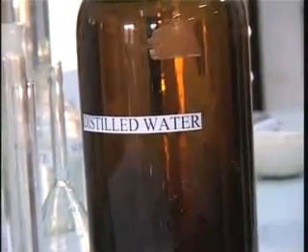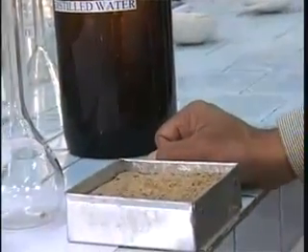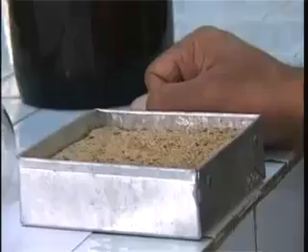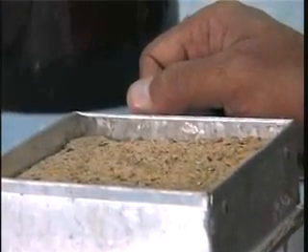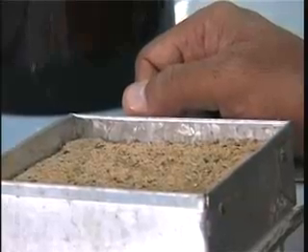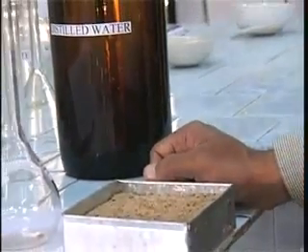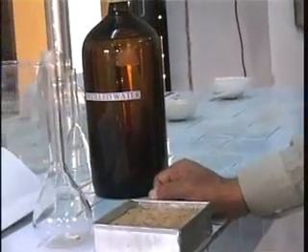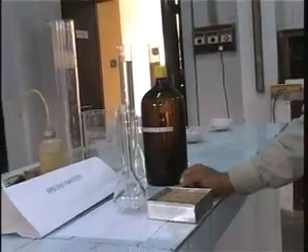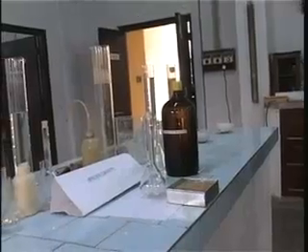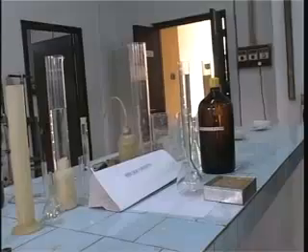We are going to take a representative amount of soil in the flask, and then we are going to top it off with distilled water up to the mark that we saw on the stem of this flask, and we are going to keep it under suction to de-air the water so that there is no bubble of air included between individual grains of the soil, because that is going to introduce some error in the reading.